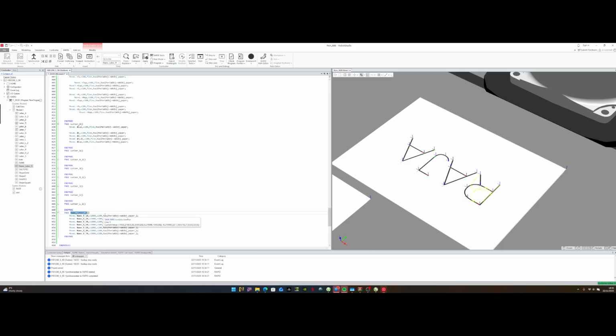Okay, so by using still the same tool pen, work object paper, all that, I'm just going to go over here, change this to V100 for all of them, one after the other. Don't worry, we'll modify everything, and then under this I'm just going to write fine. Okay, Control C, so I'll go over here.